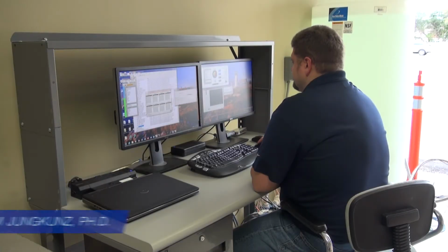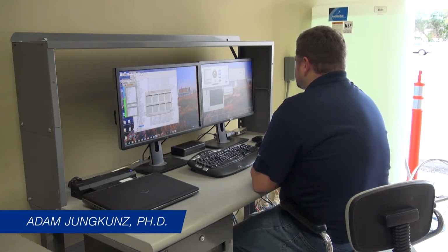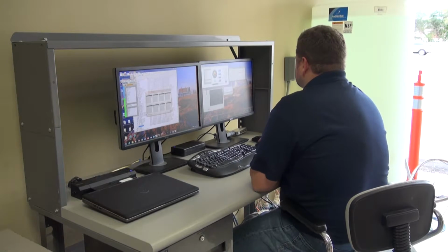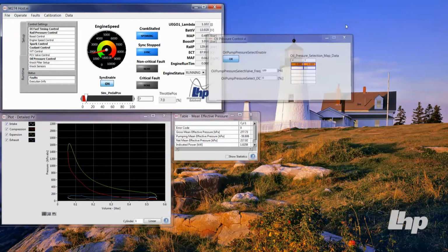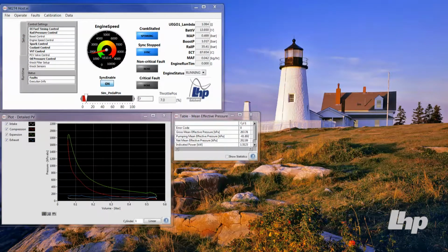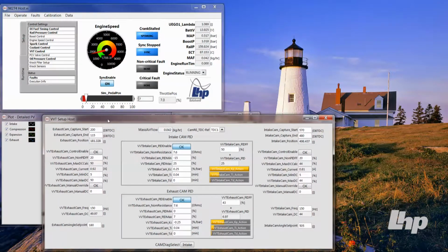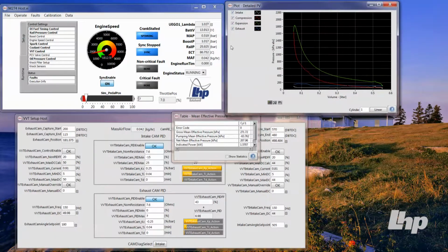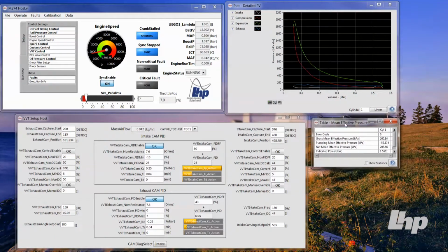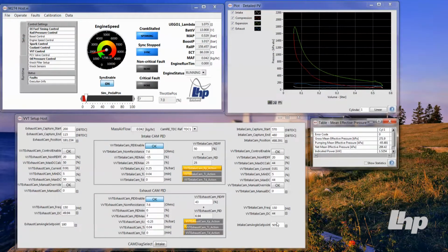This particular engine has an oil pressure control valve where there's basically a high pressure and low pressure oil pressure setting. So we're going to turn that on so that when we run our variable valve timing, we are operating in the low pressure mode. So what I'm going to do is set this variable valve timing host up on the bottom of my screen and rearrange my different things of interest so that we can change the valve timing and see how that works.